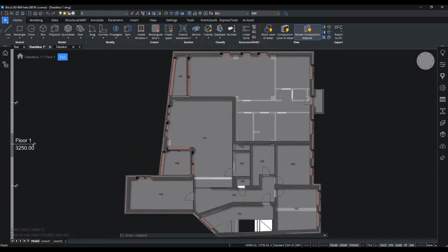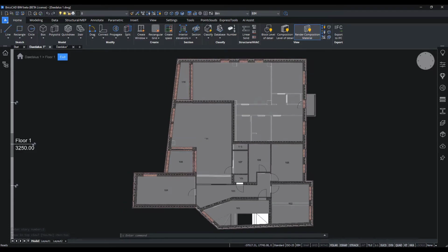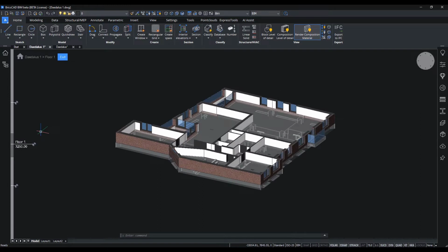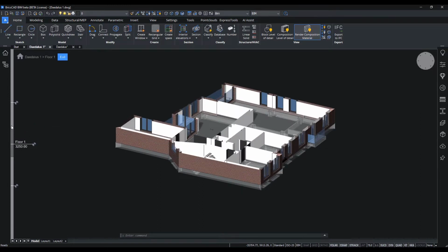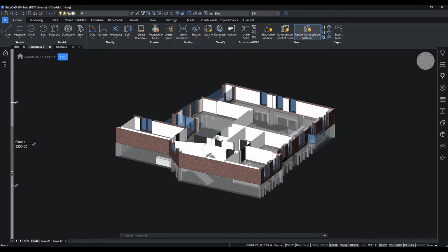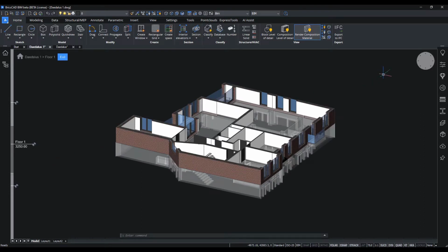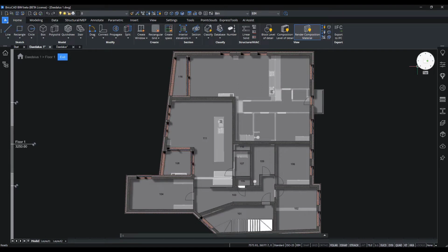We're actually still in our 3D model. A few things happened when activating this top view mode. First, the camera was set to top view and perspective was turned off if this was active. 2 temporary clipping planes were activated. I can drag these planes up and down to include less or more in the view. Finally, the floor slab and underlying geometry was temporarily set to be transparent and locked. This allows you to see the underlying geometry as a reference, but prevents accidental modification of these entities.